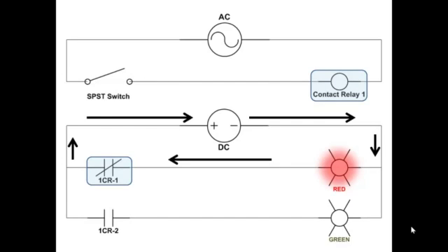So you have seen now a simple illustrated type diagram for electrical circuit, and this is a more conventional style. Typically you divide up the AC from the DC, so all the AC is located on one sheet of the drawing set and the DC is located on other sheets, because the relay contacts very well will end up on a completely different sheet of the drawing set than the coil that controls them. You have to have very good nomenclature to identify what coil these contacts belong to.